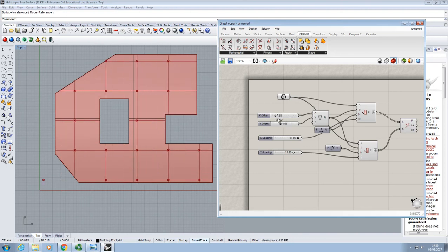But probably what you'll find as you do that is that it's very difficult to actually use only these points as your columns, because you'll end up with situations like this, where if this grid represents our sort of primary steel frame, we're going to have members sticking out here, cantilevering out with no support at the other end. And if that's a very short cantilever, then that's probably okay, I'm probably all right with that. If it is longer than a certain amount, however, we'll probably want to put another column at the end to pick up that support. Otherwise, we'll have ridiculously long cantilevers. That will be driving our structural depth. Our beams will get deeper and deeper, and no one will be happy.